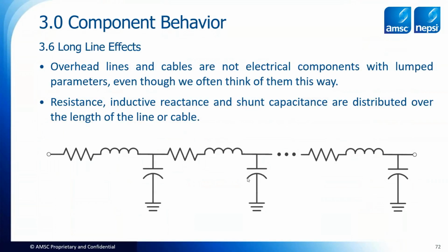You have to include long line effects, because short and medium length cables and overhead lines look longer at higher frequencies. If you remember back in school, maybe you took a power systems class, when they talked about long lines, I forget where the break point was, but it was somewhere between 20 and 50 miles.